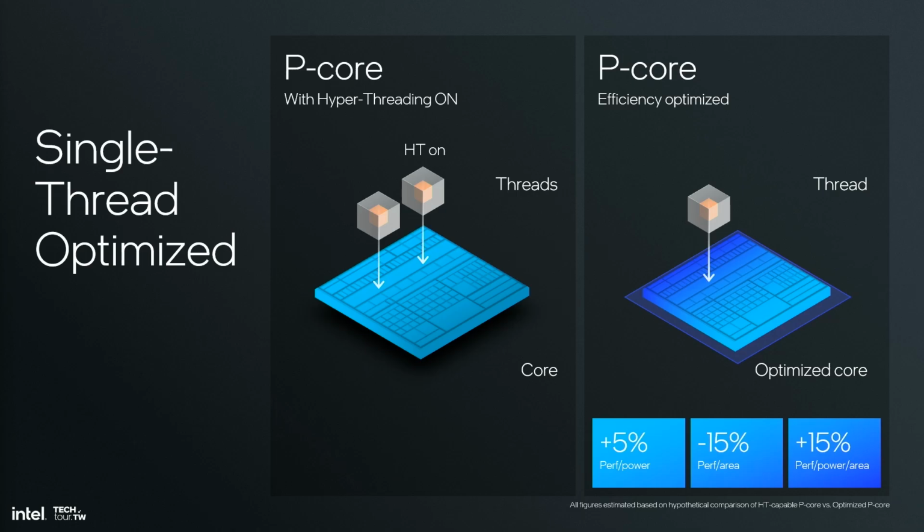Now, while hyperthreading is certainly the most externally visible feature that we've removed from the Lion Cove version that goes into Lunar Lake, it is by no means the only feature that was excluded. Other capabilities such as in-field test circuitry, transactional synchronization extensions, advanced matrix extensions, and various other features which are not enabled on the Lunar Lake platform were also removed from this version of Lion Cove. In short, our mantra was simple. Remove any transistor from the design that doesn't directly contribute to product goodness.